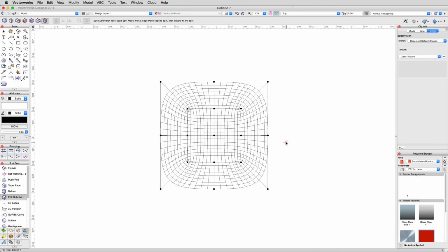The two extra edges we added gave us the more rectangular shape we were looking for, but we want more of a rounded rectangle. So let's stretch this shape out to the left and right a bit. Rather than grabbing and moving each face or edge individually, we can reshape groups of them together. Select the first editing mode, Transform. Then, click and drag a marquee around the left 6 vertices. They will then highlight in red, and the 3D dragger will appear.